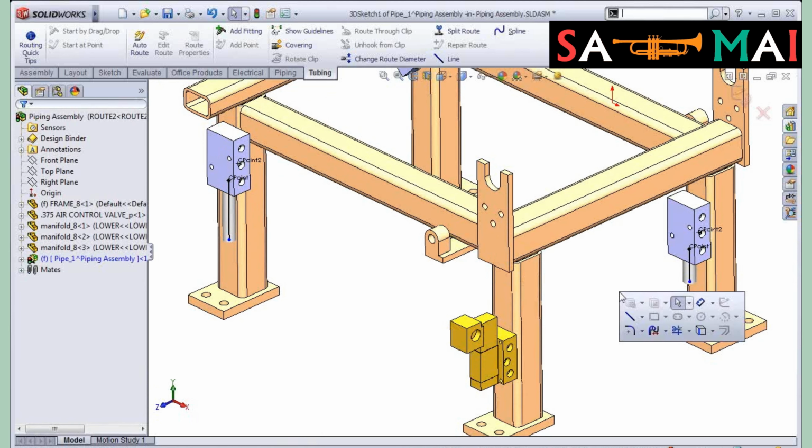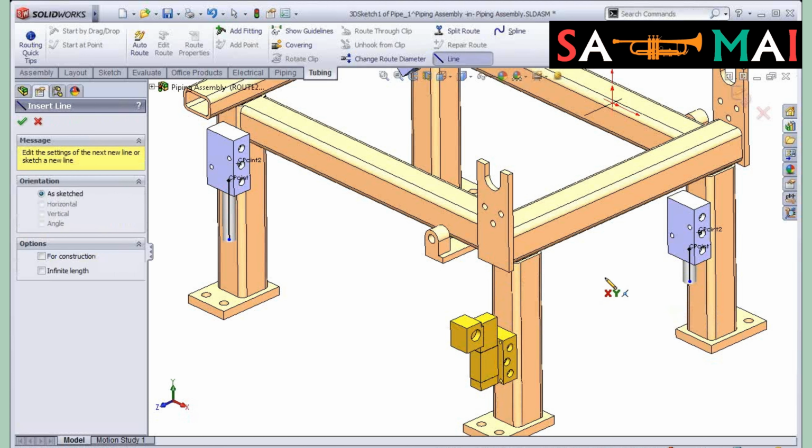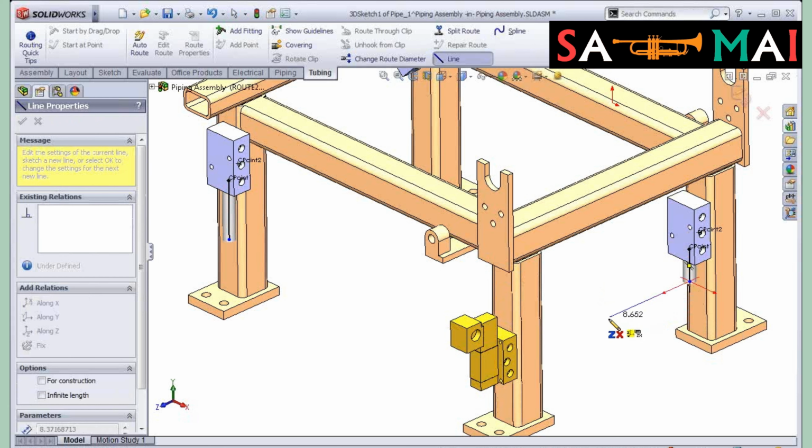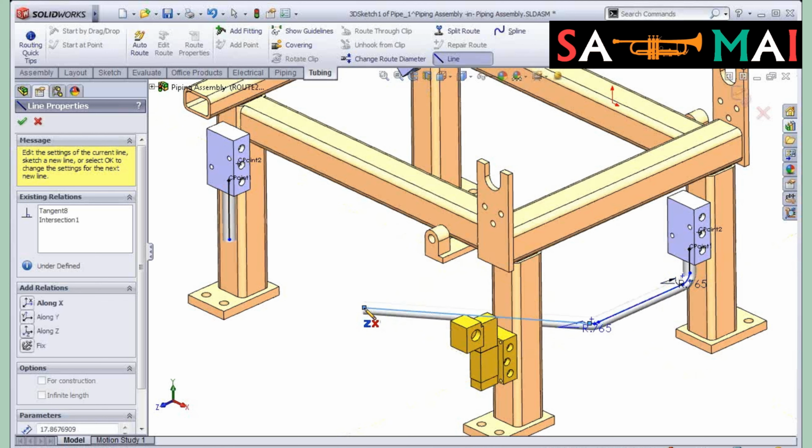Now all I got to do is connect the dots. Right? So we're going to draw lines in a 3D sketch, and we're going to stay down in the ZX plane. We're going to come out along the Z. We're going to go at an angle along the ZX, and this is why I'm doing sketching instead of auto route. Auto route's never going to give you angles unless it's the only possibility. Auto route here would have done some rigid X, Y, Z lines in those directions. I knew I wanted to come in at an angle.